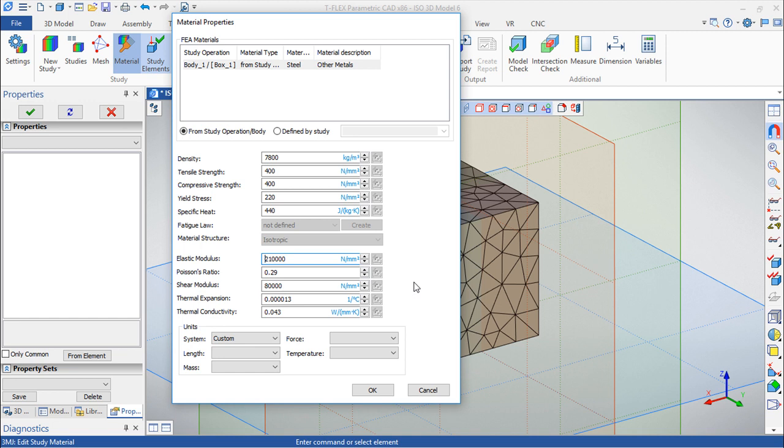And we have a couple of very important points in that graphic, and one of them is the elastic limit, which is the point until when, if the material suffers an extension or a stress, better saying, it will recover, because it's in an area that we define as elastic elongation, or it's still in the elastic area.